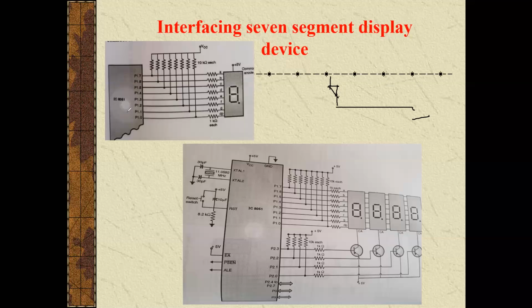To glow the LED with high intensity, a large amount of current should be provided to those LEDs. The microcontroller is the source of that current, but the source cannot provide more than 2 milliampere. If the current increases beyond 2 milliampere, the LED will also be affected, so we cannot connect the anode terminals directly to the port. Also, we use this circuitry, connecting resistors to VCC.